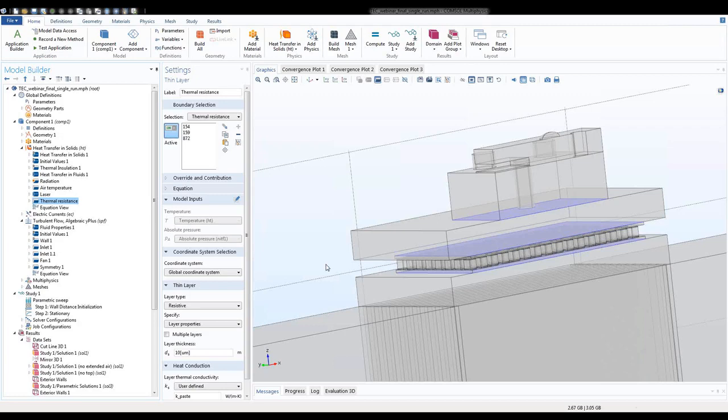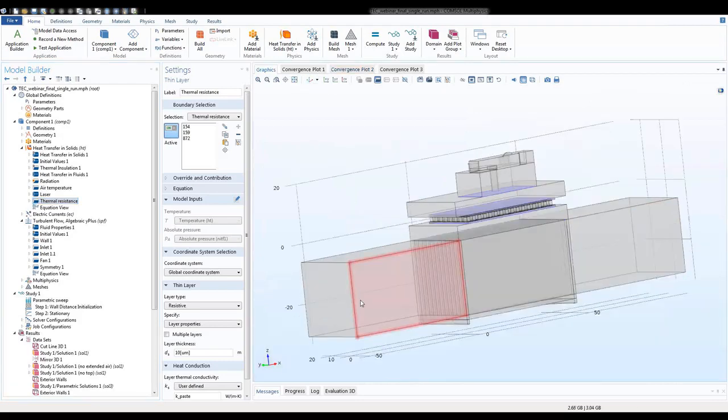Now it's an internal boundary and it's automatically set to be floating, which means it's unknown. In this case, the continuity boundary condition is automatically imposed. What do you think determines the hot side temperature? It's a temperature boundary condition set to the outer boundary and radiation condition. This is the key.